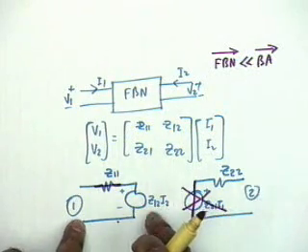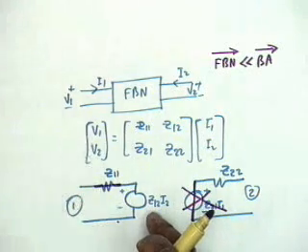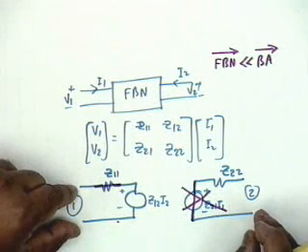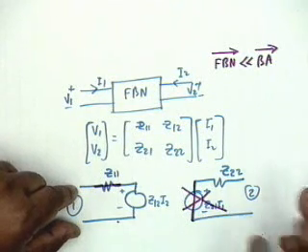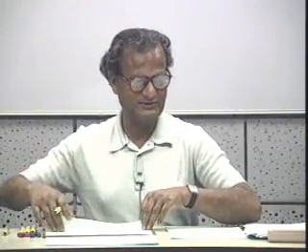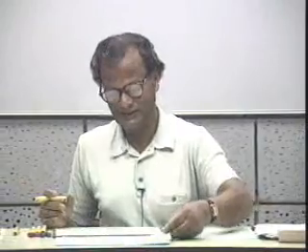To be able to measure Z12, or beta (Z12 is now equal to beta), what you have to do is apply a current source here and measure the voltage under open circuit conditions, and that gives you Z12. This is the total justification. In the other two, I will not make this justification. I will simply draw the A circuit and the beta circuit. But before that, let me take an example.